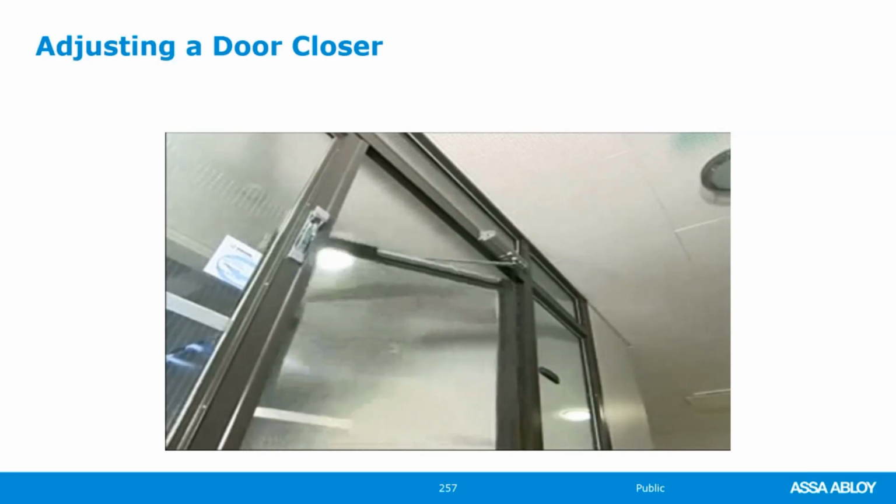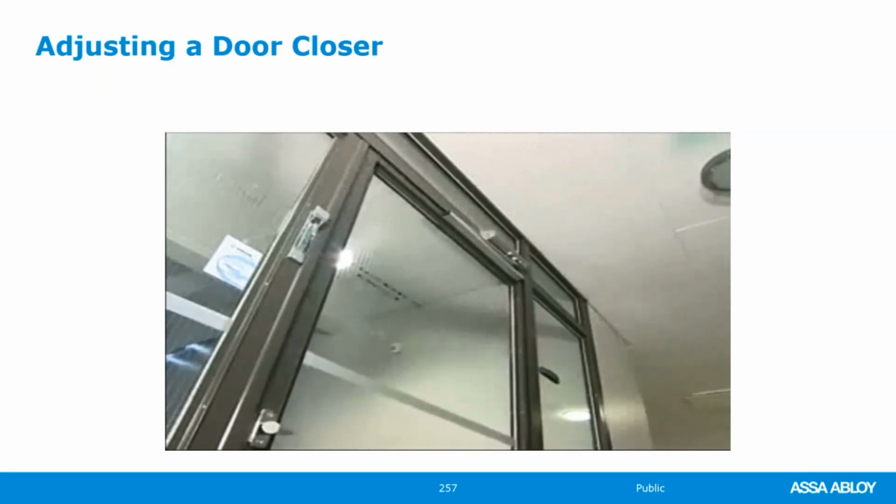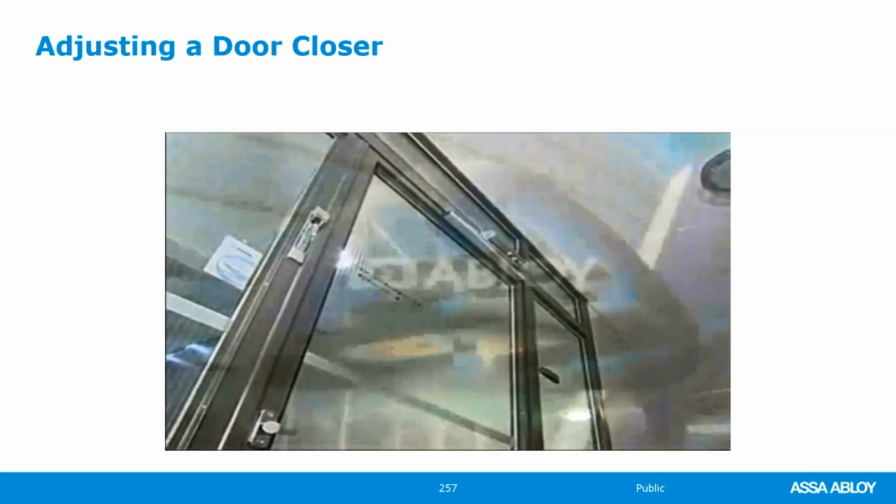It still meets the fire rating. You can use delayed action with a door closer because you can adjust it for up to, I believe, 30 seconds. And it's not holding the door open, it's just closing very slowly. And once that time of the delayed action is reached, then it continues on.